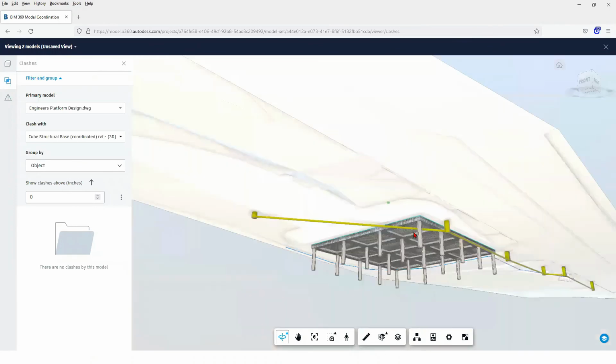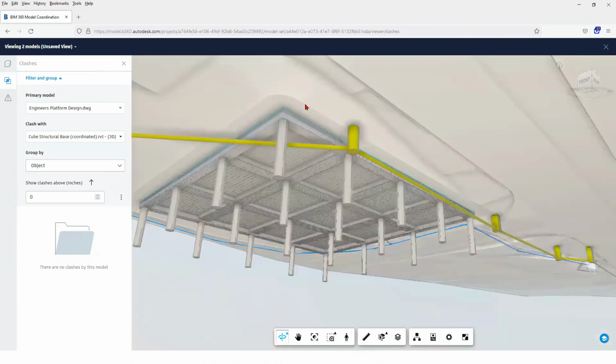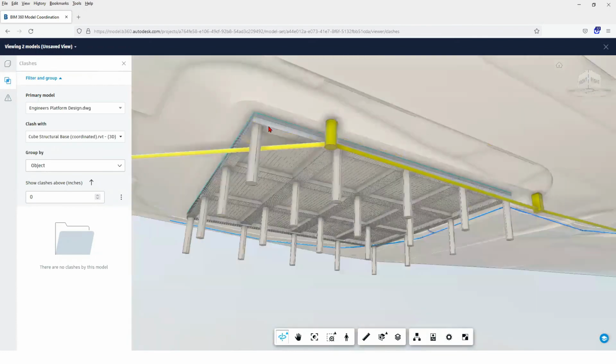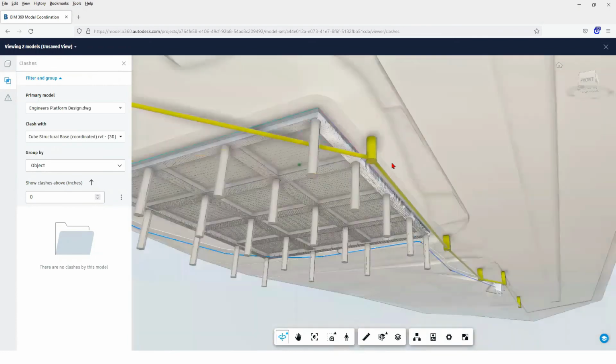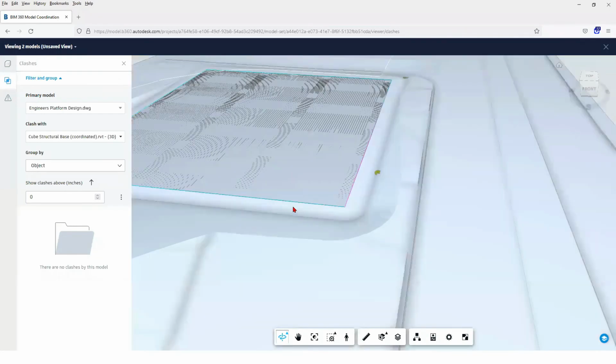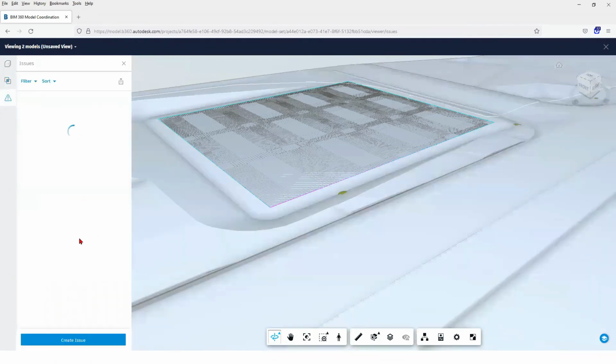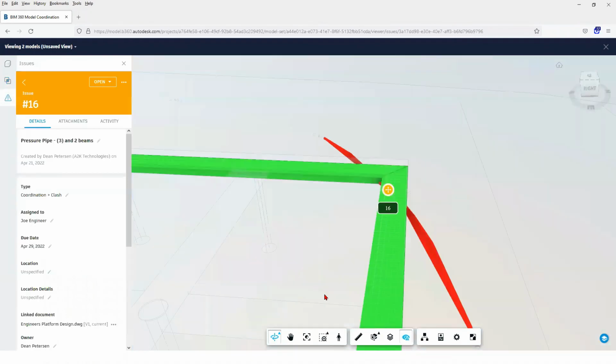Now, here's our 3D model. You can see everything. That one's okay. It's going under. If you're assuming you can, I'll want it under the slab. But everything gets checked in 3D space, and the clashes, just by putting them into those coordination folders. We have a list of the issues here. So any issues raised should show the one we just did. Here it is, and we can click on that and go and find it, and that's the information around it.